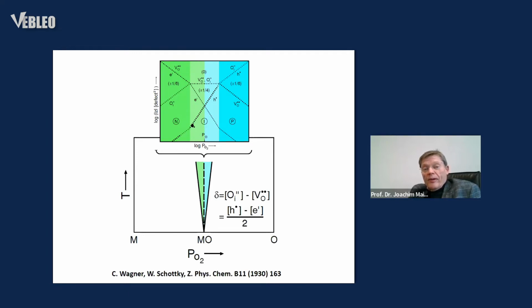that is shown in this complex diagram. It is of dramatic influence on ionic and electronic carrier concentration. So when you go through this tiny thing, the electron concentration goes down a lot, excess electron, N-type. Hole concentration, P-type, goes up a lot. Vacancy concentration, so the ionic important species, goes down a lot, and the oxygen interstitial goes up a lot. So you change essentially this material from an N-type, maybe via ion conductor, to a P-type conductor, only by going through this ppm maybe of phase width. And this is most important.